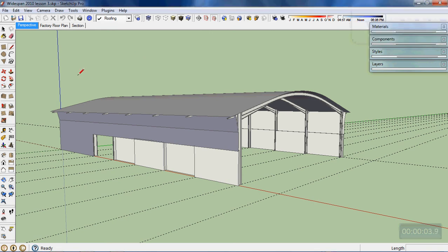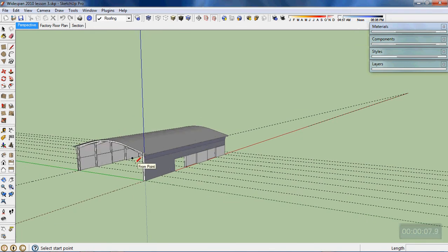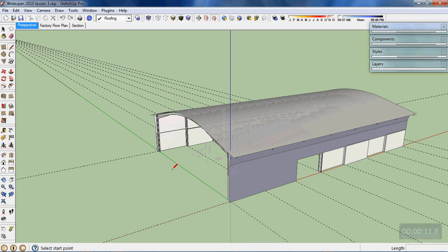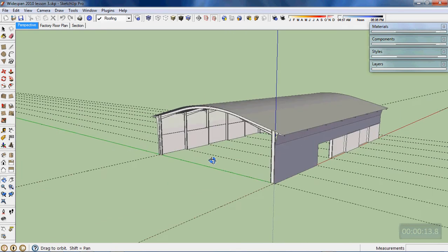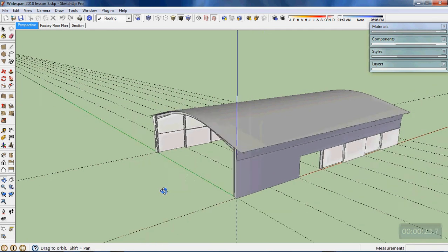So we'll close off the end wall of this building now, this back wall. To do that, we'll put some end bay support columns in at third equal spacings in between this grid. So just for now, I'll temporarily divide that up.